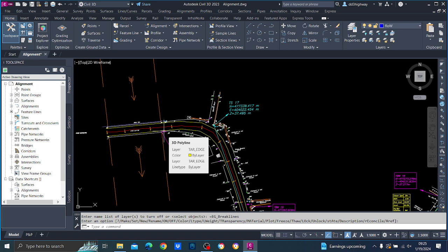Because there is some theory behind it. You have to check what your design speed is. Depending on that, what is the minimum curve radius that you can apply, and if you are going to go for compound curves, what are the restrictions? If we are going to go for a reverse curve, what are the restrictions? These things you have to know. That is why we engage engineers for highway design. Otherwise drafting is nothing.